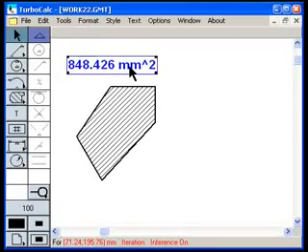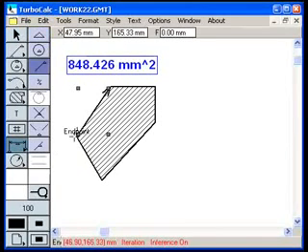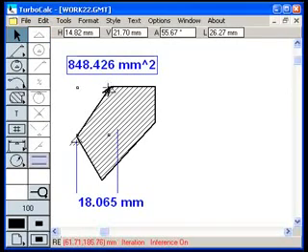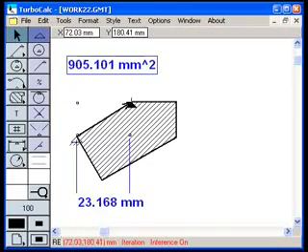In TurboCalc, you can work with millimeters, inches, or any unit system of your choice. Unit checking is performed automatically for every calculation. You can also use the dimensions to automate a calculation. For example, I want to calculate the distance between the centroid of the shape to the edge. So take the dimension tool, constrain one end to the endpoint, the other one to the centroid, and here is that calculation. And now if the geometry changes, you'll see just like a spreadsheet, everything is updating automatically in real time.